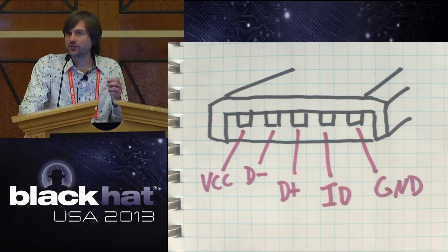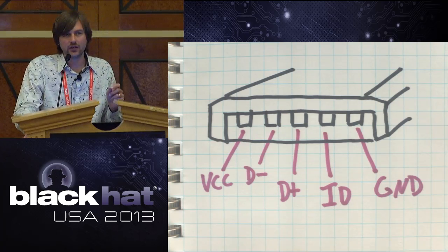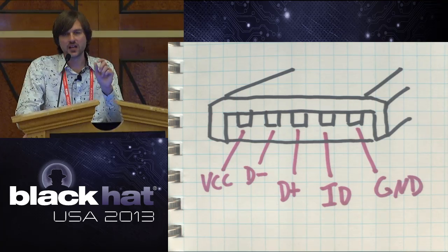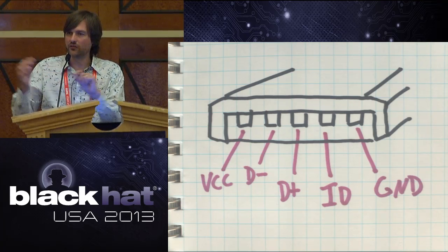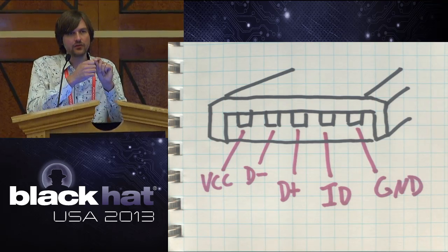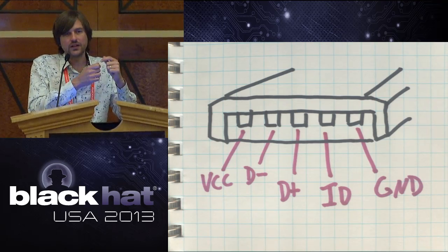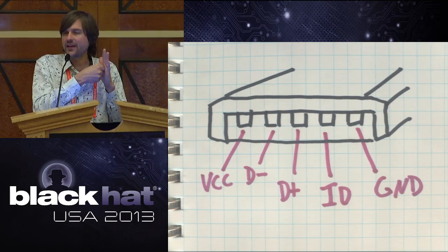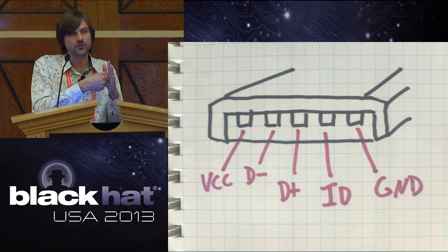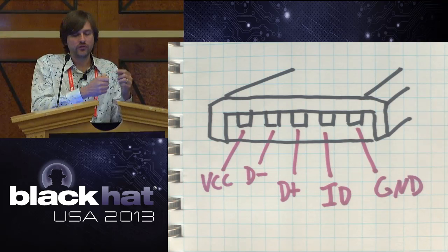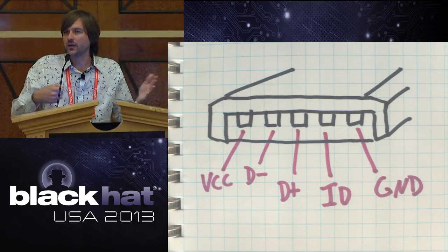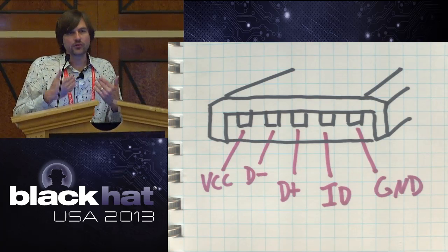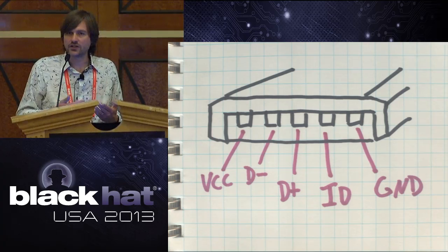And it's a pin whose purpose was originally intended for USB On-The-Go. If you're making a cable, you connect the ID pin to ground if you want that cable to tell the device you're plugging it into to switch into host mode. Or you leave the ID pin unconnected and plug that in, and the device assumes that it's in device mode. And that's the crudest form of accessory detection.